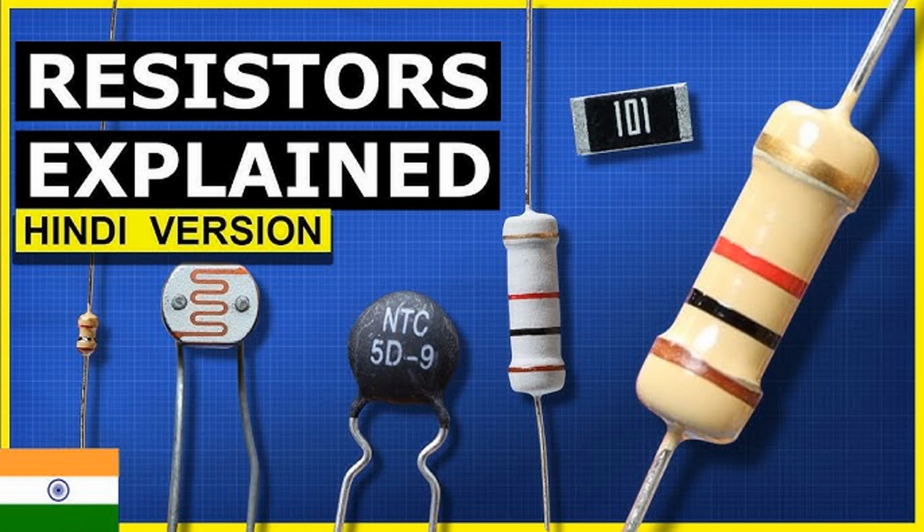Applications of pull-up and pull-down resistors. Button debouncing. Purpose: Buttons and switches often generate noise when toggled, which can cause multiple transitions to be detected. Pull-up or pull-down resistors help ensure that the input pin reads a stable state when the button is not pressed. Example: A button connected to an input pin with a pull-up resistor ensures that the input reads high when the button is open and low when the button is pressed, connected to ground.